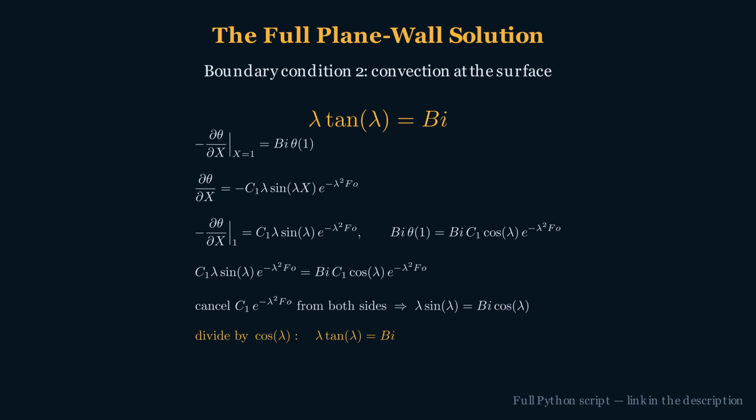This is transcendental; it can't be solved in closed form algebraically, and it has infinitely many roots, lambda 1, lambda 2, and so on, one for every possible mode of the temperature distribution.